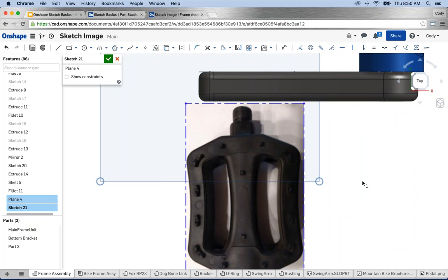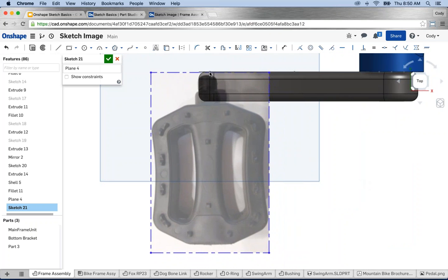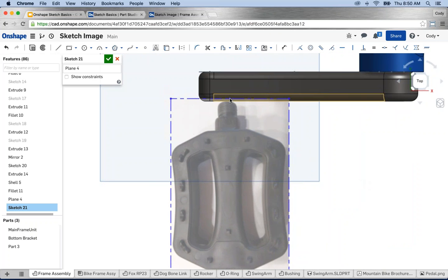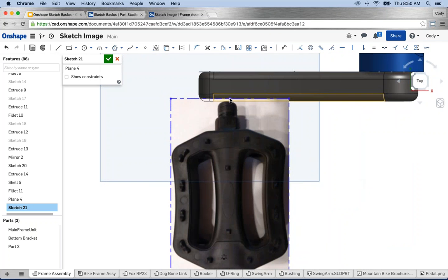You can constrain the rectangle like it's a normal rectangle. So it's a great way to get the petal, in this case, exactly where I wanted it. I could come in here and add some kind of a midpoint along this line, and then move that midpoint and attach it to some other sketch entity. So it's a valuable way to go in and constrain it very easily, without a lot of energy.